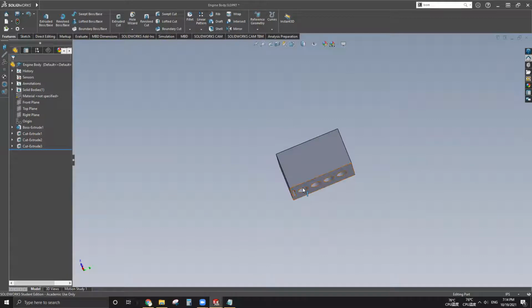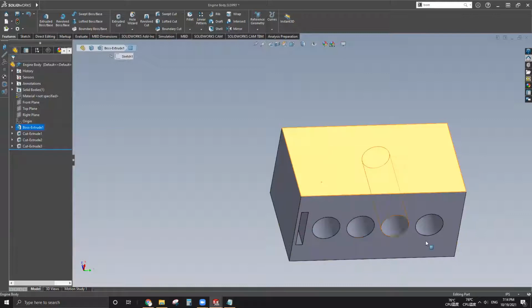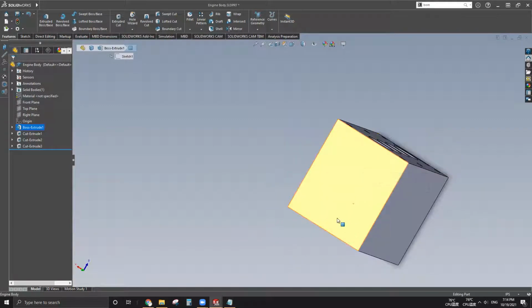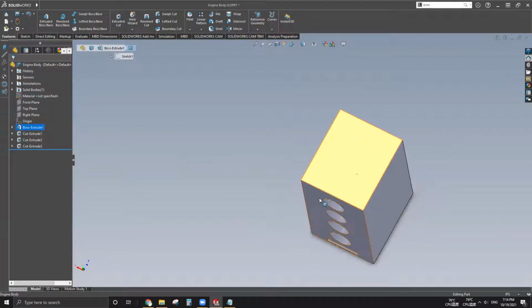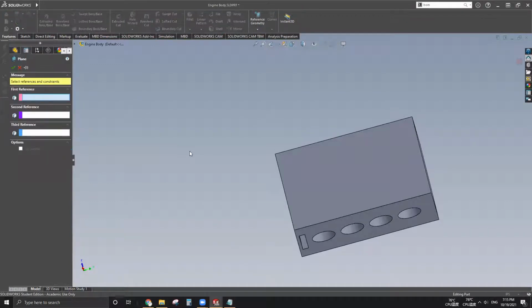All right. So at this bottom, we have nothing. And in order to start with that extrude cut, we cannot start from any visible surface from what we see. Otherwise, it will start cutting from here, right? But no, we want the surrounding wall to be intact and the feature only take place internally, right? So that means we have to make a plane. You can search plane right there, or I have it right here. We have to make our own plane to start with the